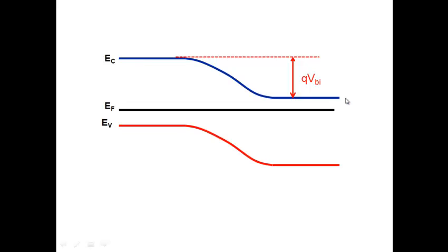Positive voltage here. Let's not worry about the junction first of all. Far away, I have a semiconductor connected to a positive voltage. All its energies will go lower, right? By how much? By the amount that I've applied here. So the diagram will come down by the applied voltage. Keep that in mind. This side remains the same, still connected to ground, and this side has gone down by qV.